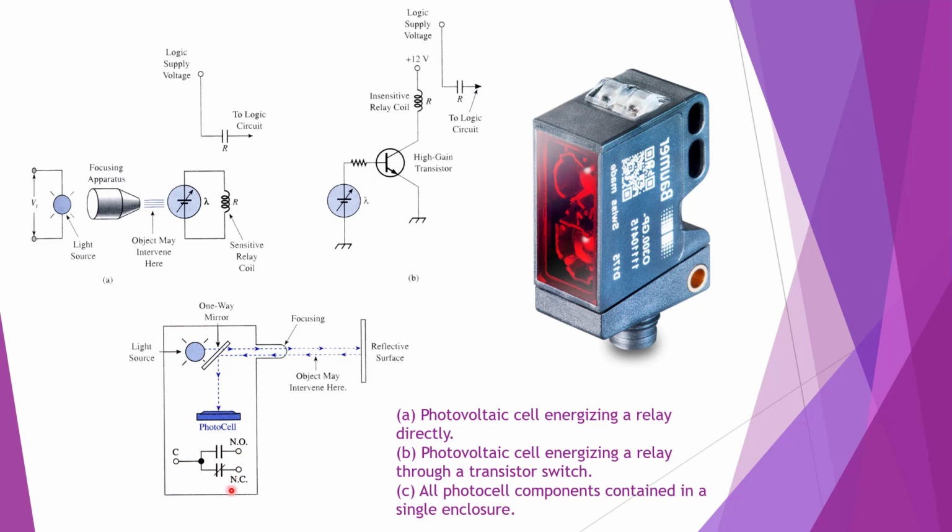And my circuitry that we saw up here is included in this. So I've got a couple wires, terminals on this. I've got three. If you look at the bottom of this, there's going to be 3 screws, one for power going in and 2 for coming out, one on a normally closed set and one on a normally open set.